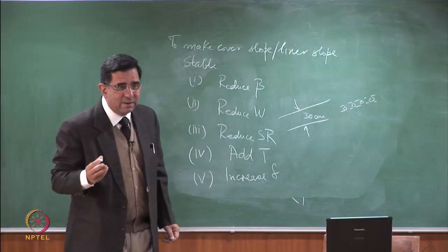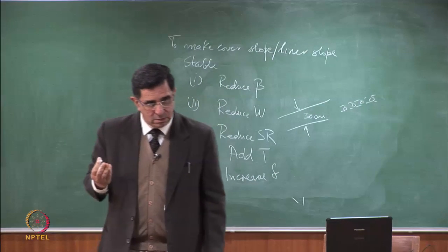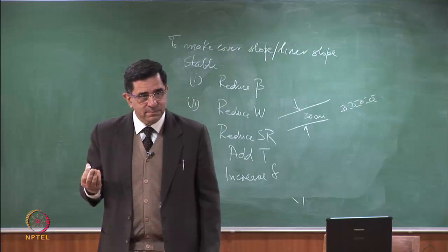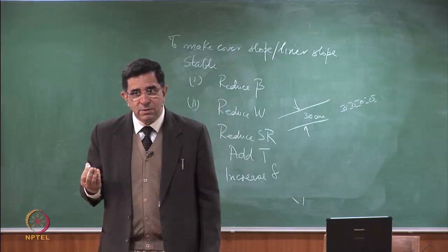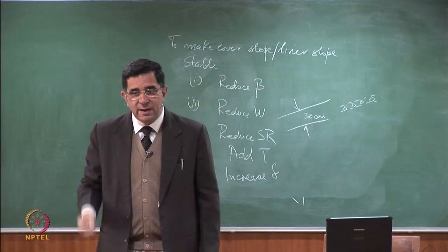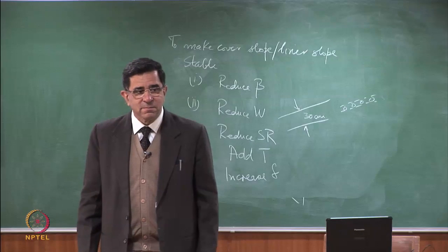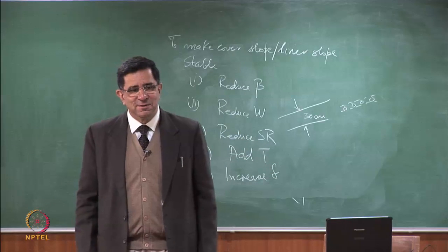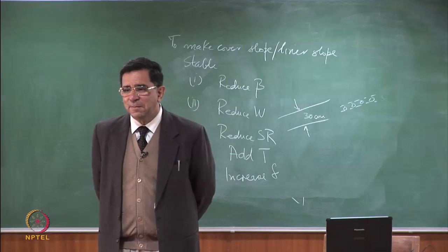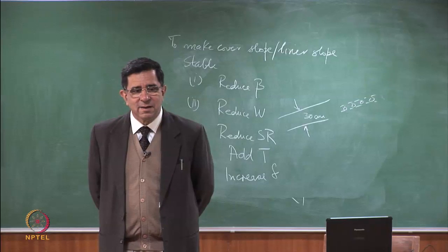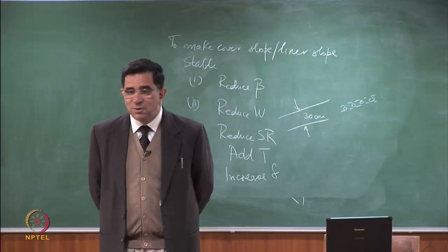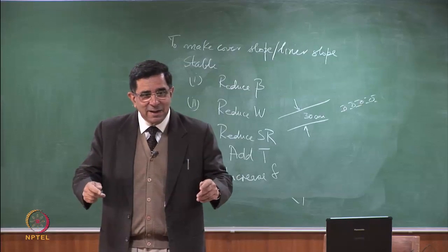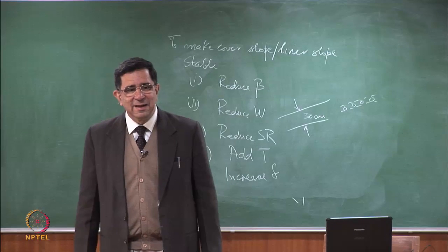So in the case of sand, when I use a textured geomembrane, what is delta? 25 to 5, right? To increase delta, 25 to 5. Can I make my delta more than 5? I'll make my geomembrane really, really rough. Will delta become more than 5? No, it seems if it is smooth, it is less than 5. If it is adequately rough, it's equal to 5. If it is more than rough, will it become more than 5?